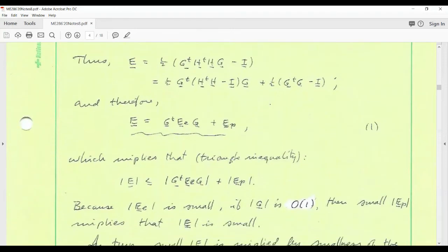So you can think of the strain as a 6-dimensional vector, right? The strain belongs to the vector space of symmetric tensors, just like any other vector space. It's 6-dimensional. As in any vector space, we have something called the triangle inequality, and we also have, for example, the Cauchy-Schwarz inequality.